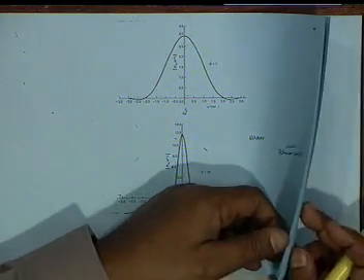So in window design, the other point to notice about the Hann window is that effectively the length is capital N minus 2, isn't that right? Because 2 of the impulse response samples would be 0. The length was capital N, 2 gone, so it becomes N minus 2. You are not able to utilize the efforts that you have put in aiming for a length capital N. The effective length becomes N minus 2.